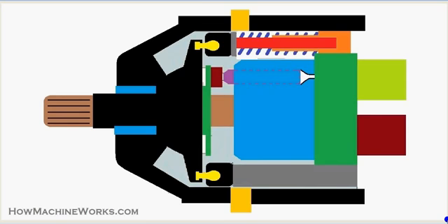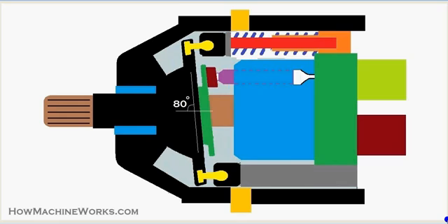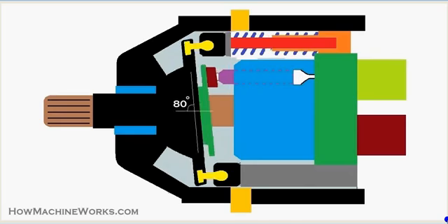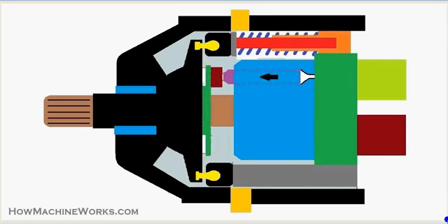So I'm pressurizing the valve so that the swash plate angle can be changed. You can see it's at 90 degrees. When the pressure hits, the swash plate angle changes to 80 degrees. You can see a decrease of 10 degrees over there. So at the top, the swash plate moves back, and at the bottom, the swash plate moves towards the front. And have a look at the piston. See the arrow mark. The piston is actually moving back, and that's the reciprocating motion happening.